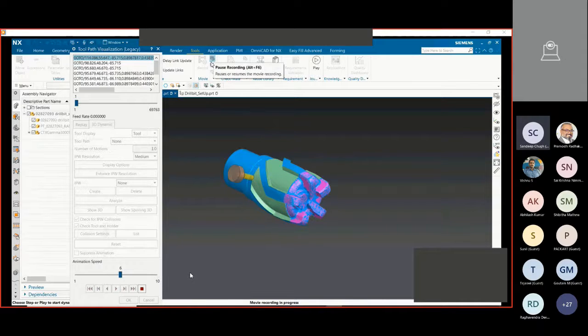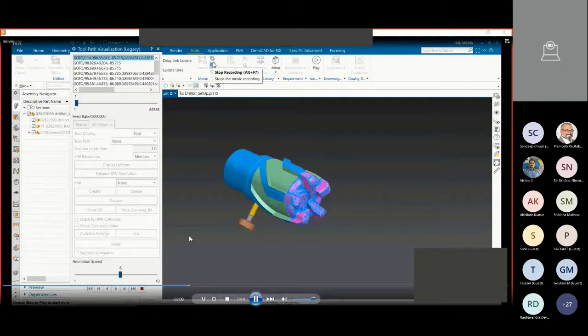It will generate the toolpath based on part and IPW, and will remove the material after leaving the stock which you had given. It's a 4-axis toolpath, mill rotary. Then in the same, we can finish the flutes areas.